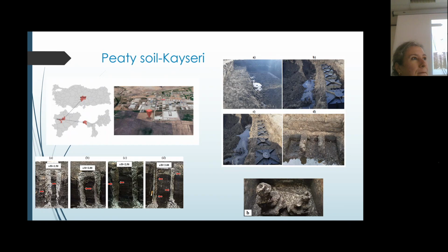We collected some samples of Italian organic soils and performed several cyclic tests. Our soils are usually quite soft, of course, so they are prone to seismic amplification, and they also have a very linear behavior with a very small dissipation of energy. So they are quite problematic because in case of earthquake, they amplify the seismic response a lot.